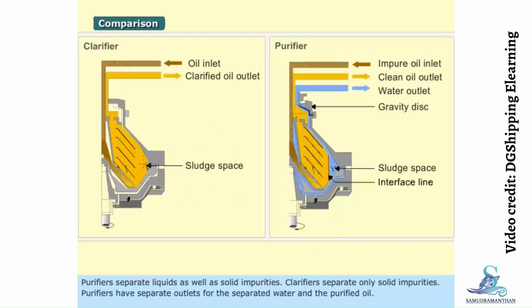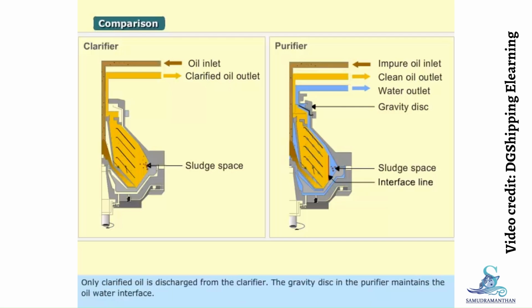Purifiers separate liquids as well as solid impurities. Clarifiers separate only solid impurities. Purifiers have separate outlets for the separated water and the purified oil. Only clarified oil is discharged from the clarifier. The gravity disc in the purifier maintains the oil-water interface.